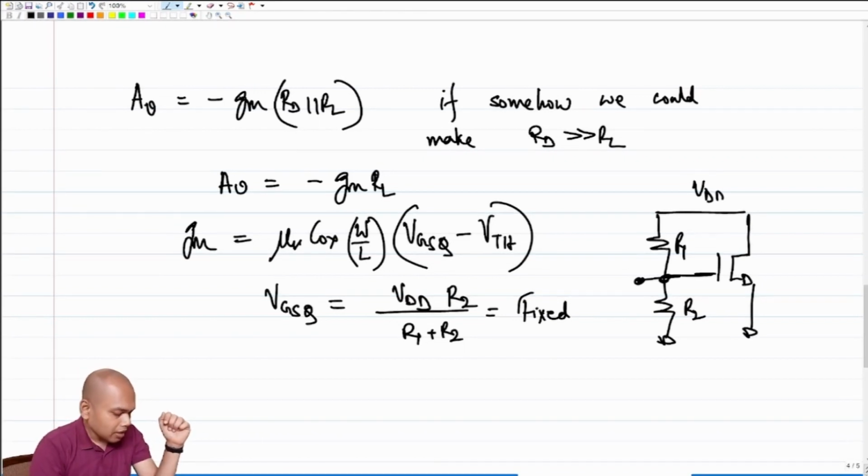the channel. And clearly, if you raise the temperature of the device, all the lattice structures and all the stuff that you learn in your device physics courses will tell you that the mobility of the electron changes. Most likely, the mobility of the electron goes down. Similarly, the threshold voltage of the device is also a function of temperature.